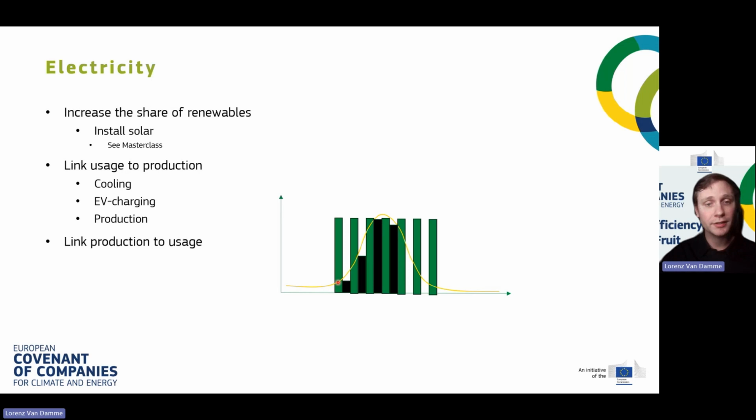charge all vehicles. If this wouldn't have been the case, if we do not have enough production during a day to do this, because it's winter or any other reason that we maybe do not have a large enough PV installation for this, then a smart algorithm would start somewhere in the afternoon to charge, even if there is not enough solar production to cover this.